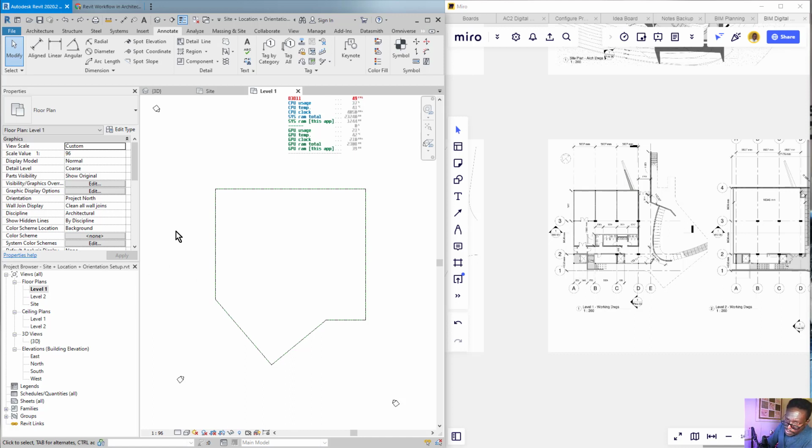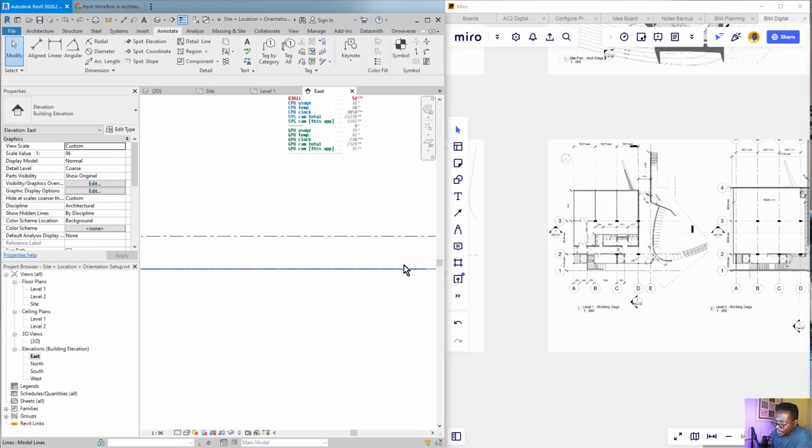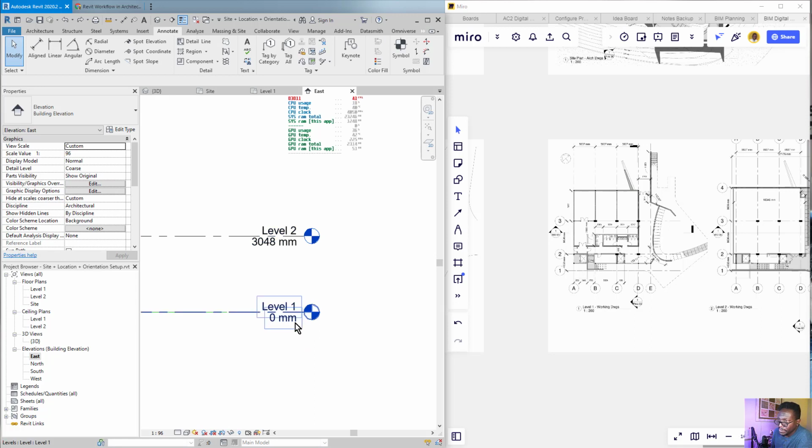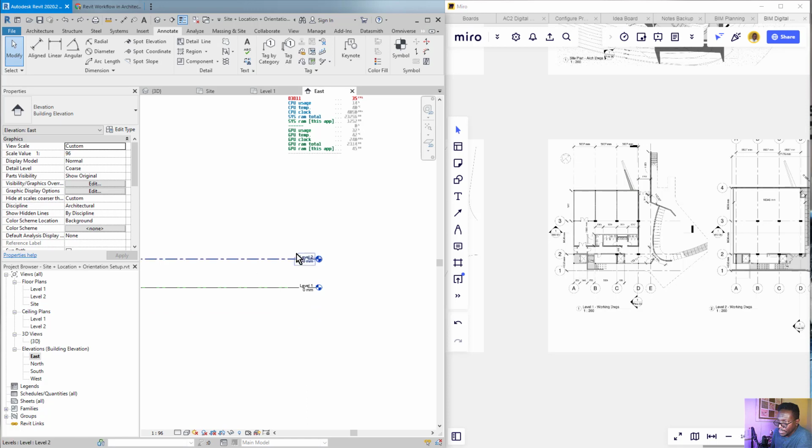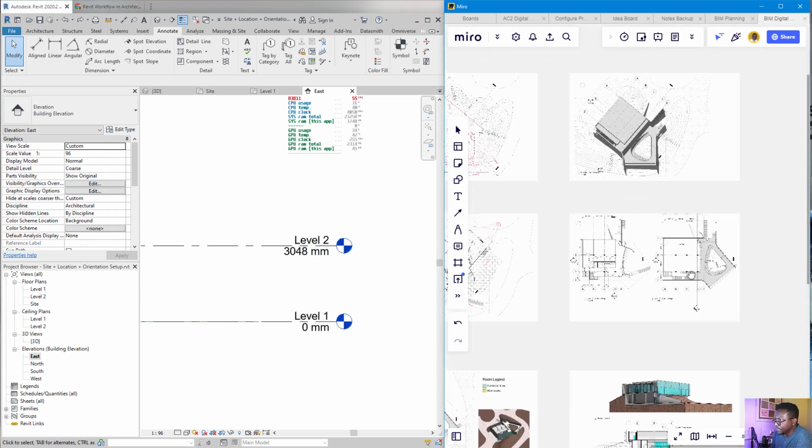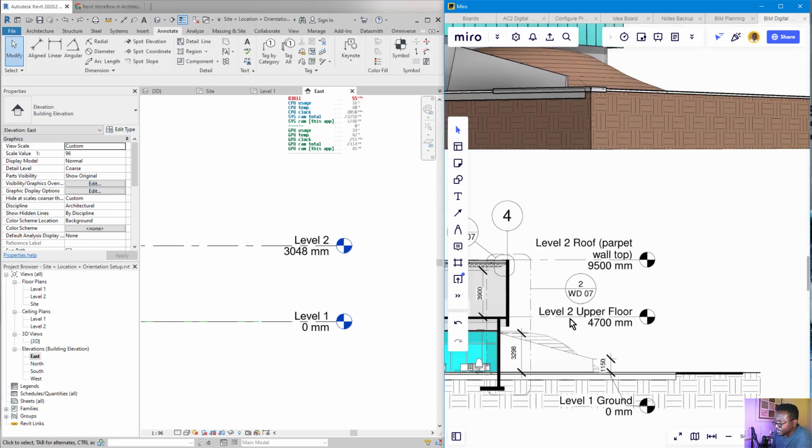All right, now to get things started, let us look at the levels we currently have. Now, a good way to look at our levels: you can't see levels from a top view. So the best way to look at your levels is either in 3D view if you have Revit 2019 and up, or you can look in an elevation view. So if I choose any elevation view at random, you will see that I have my levels here.